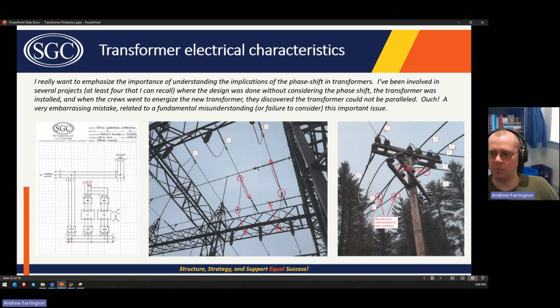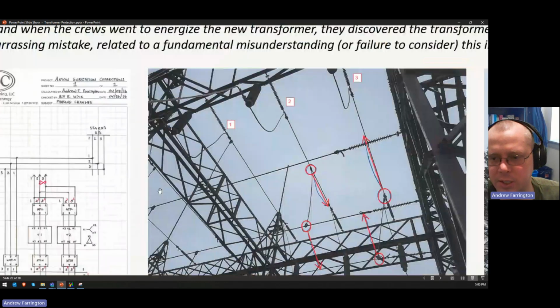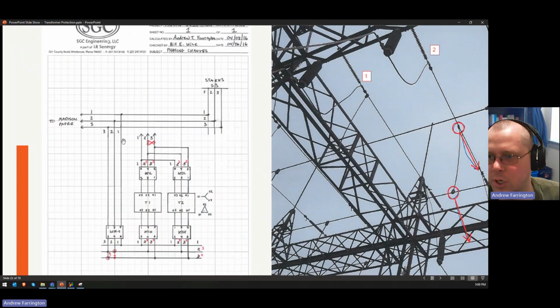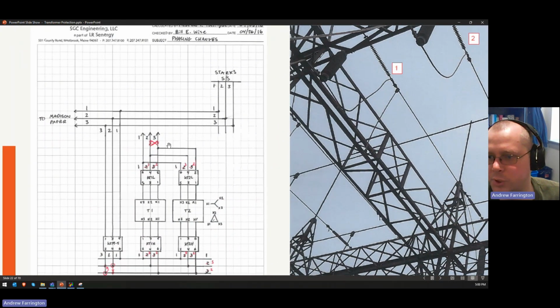And they agreed with all of the recommendations and they were excited to implement them. And so we were working with them to come up with an outage sequence plan so that they could take their substation out of service, make the changes while minimizing the impact to their customers. And they said that they actually had a tie switch that tied their 34 kV system, which is here, the 34 kV system, over to a local utility.